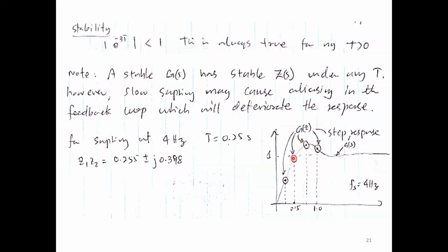The samples are not actually enough, but you can see you are capturing the waveform. That's all right. But if you further reduce this frequency to maybe 2 hertz, then you are missing this one, and you are also missing this one. So you have this sample and another one over here. Then you have trouble plotting the graph. That is the problem. You have no idea about the actual shape of the curve looking at the samples.